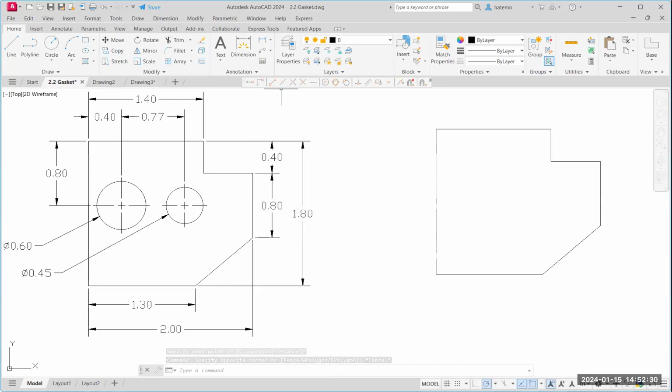So the first thing that you do when you're going to use this object snap is it's actually going to override your object snap for the whole drawing. So for example, if I want to make sure I hit an intersection or a midpoint and it keeps snapping to an endpoint, I can come up here and choose that option. You know, here's your midpoint, here's your intersection, and so forth. And again, we'll keep talking about these as we move through the semester.